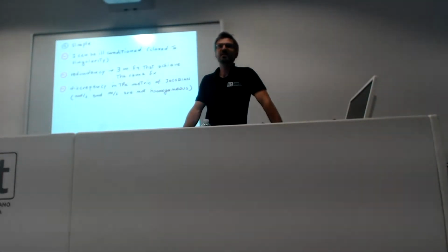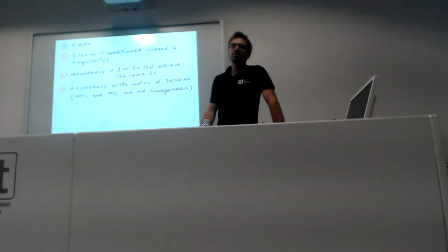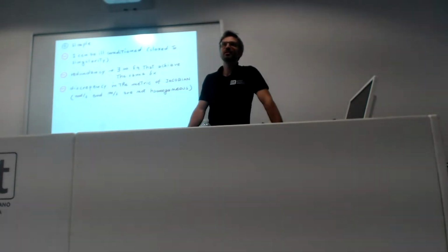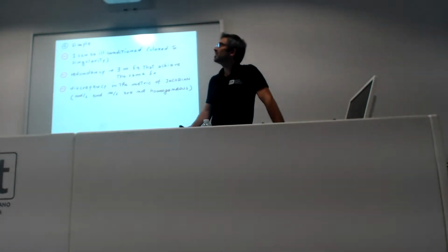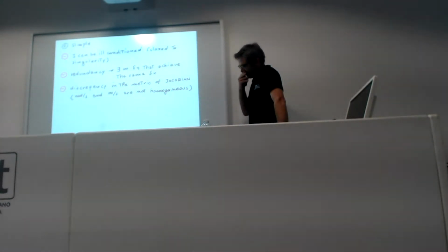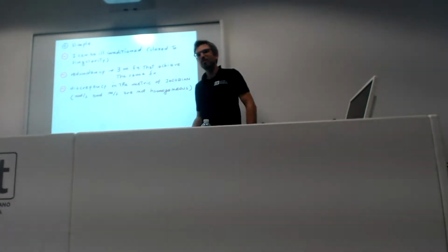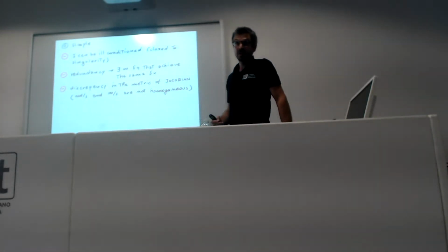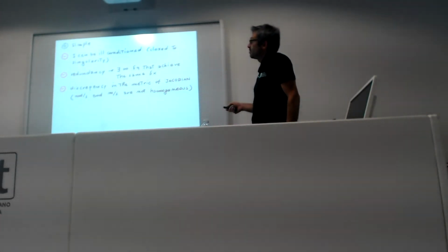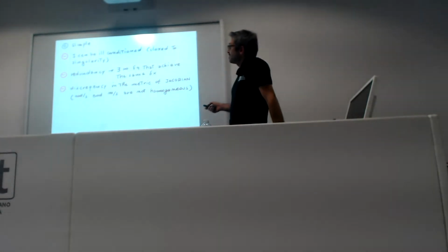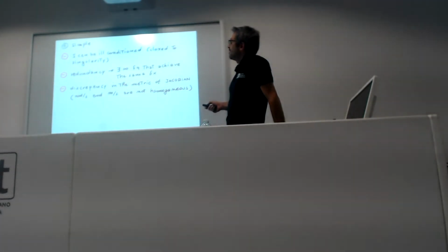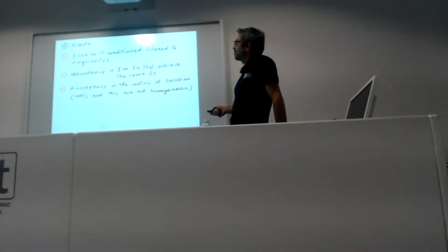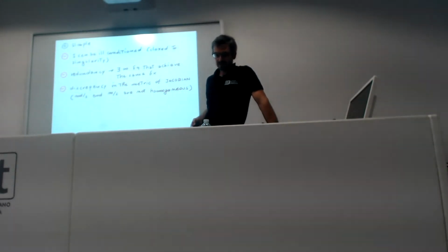The linear position error. Meters. And what is the unit we use to measure the orientation error? Radians. So we have a mismatch in the metric that we use to compute the error in position with respect to the unit that you use to compute the error in orientation. And this inhomogeneity is not taken into account here because we map everything through the Jacobian into joints.